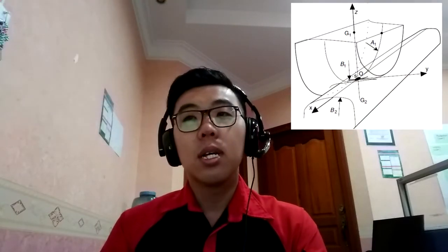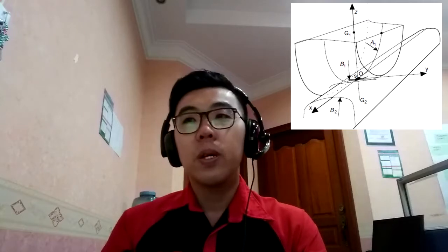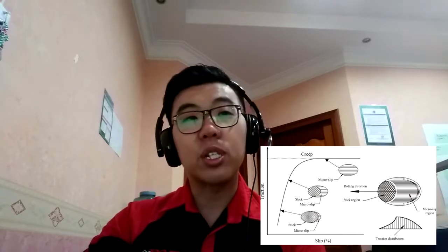Right, first of all, introduction to friction management. The wheel-rail contact is a complex and imperfect link due to the small area and being loaded with highly concentrated stresses. The conical wheel shape makes the wheelset a mechanical amplifier limited by the transverse plate with partially sliding surfaces. From this figure, we can see that the contact patch is made up of two regions: one is the stick region and the other is the micro slip region.